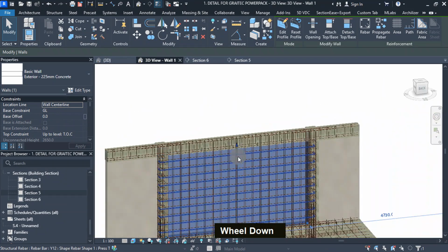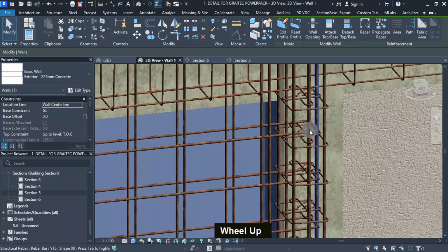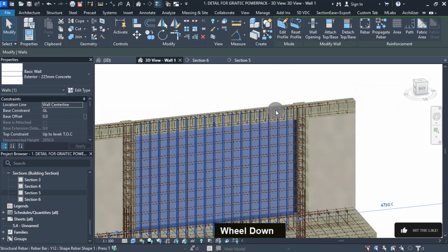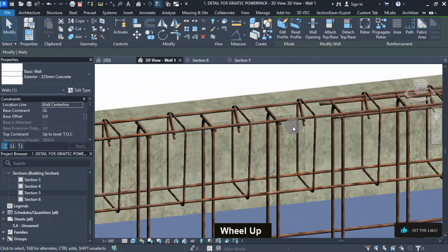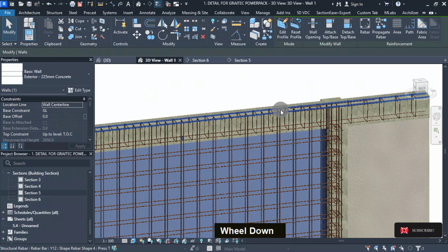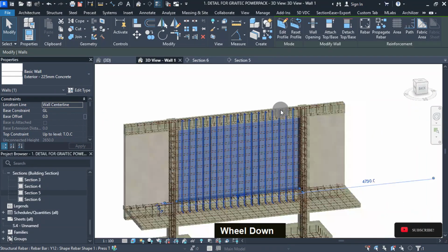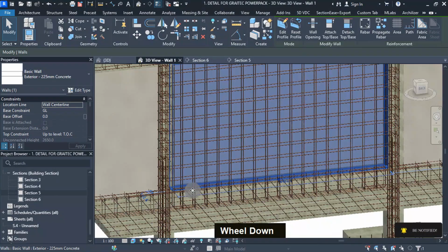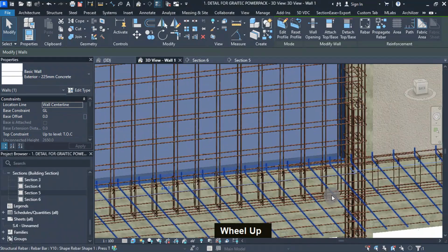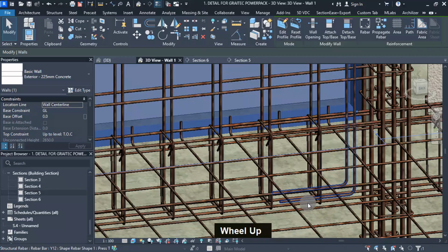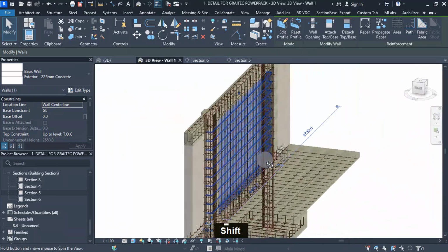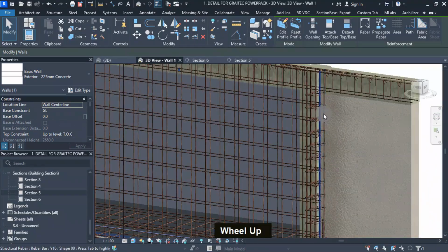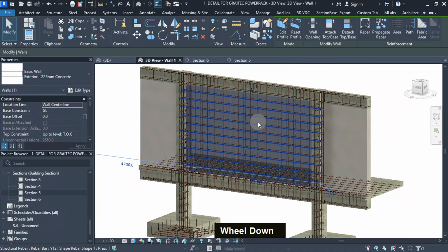At this other wall end, the horizontal wall bars have been extended to the exterior column rebar too. At the top, you can see how the bars have been integrated with the beam. You can modify the rebar properties such as length, cover, hooks and bends by using the main bars command. I can rotate to the other wall face, then explain how to add U-bars to the wall edge.